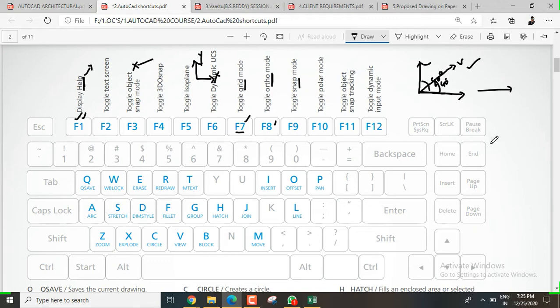And snapping. Snapping means, if you have a line here like this, here we have a midpoint. If you turn on the snap mode, you can easily pick this midpoint. If you turn off the snap mode, it will never show you this midpoint. It will never indicate it when your cursor is near. So at that time you need to turn the snap modes on or off, along with the polar mode and object tracking snap, and you need to check these things once again.